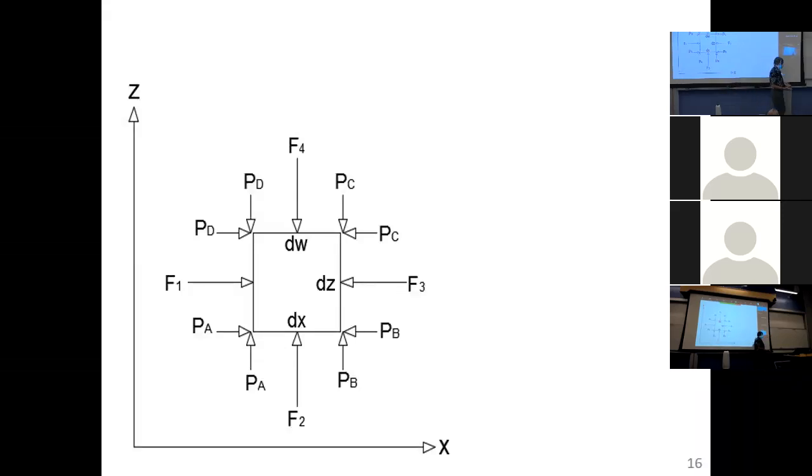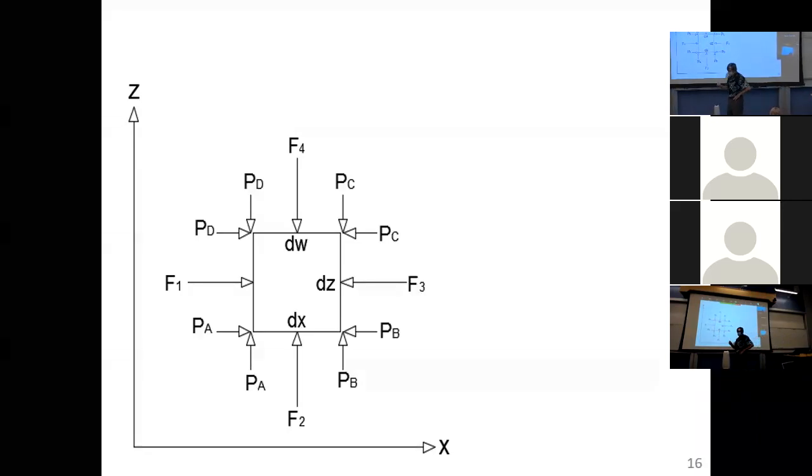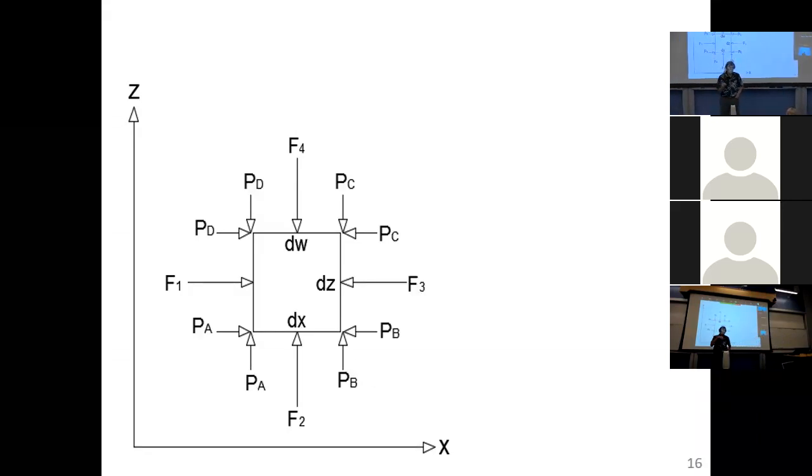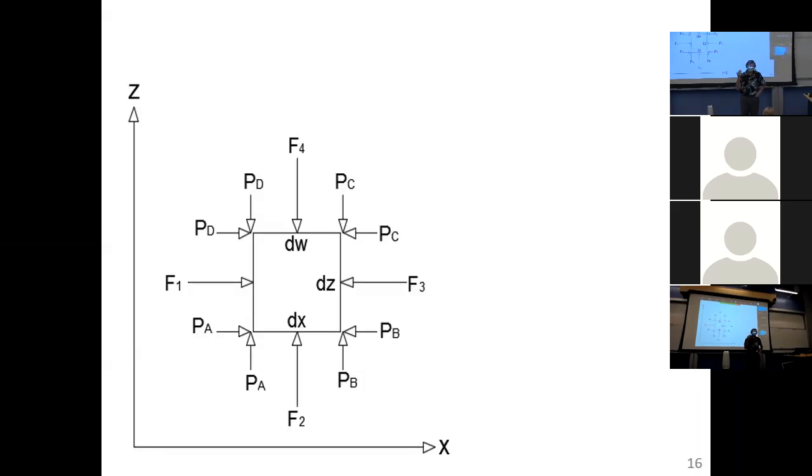And we assumed that pressure was varying as you move through the system. So if we moved from the lower left-hand corner A to B, we had a change in pressure from PA to PB. Pressure is a scalar quantity. That means that it operates the same in all directions at a point. When we integrate pressure over an area, we get a vector, and that's a force.